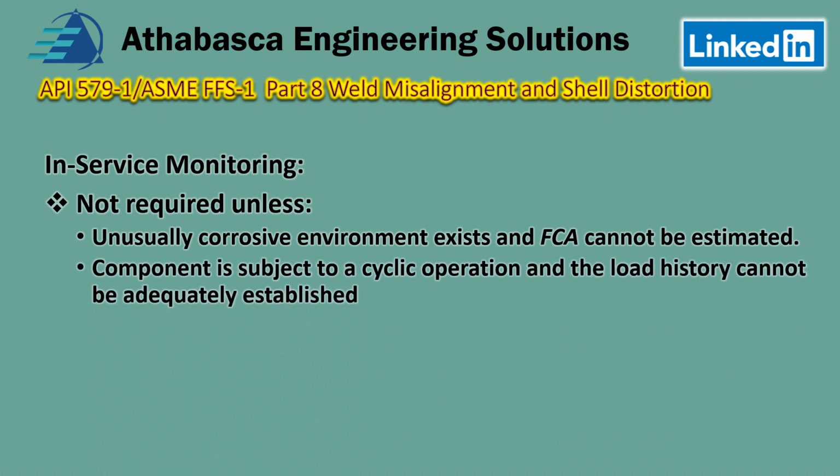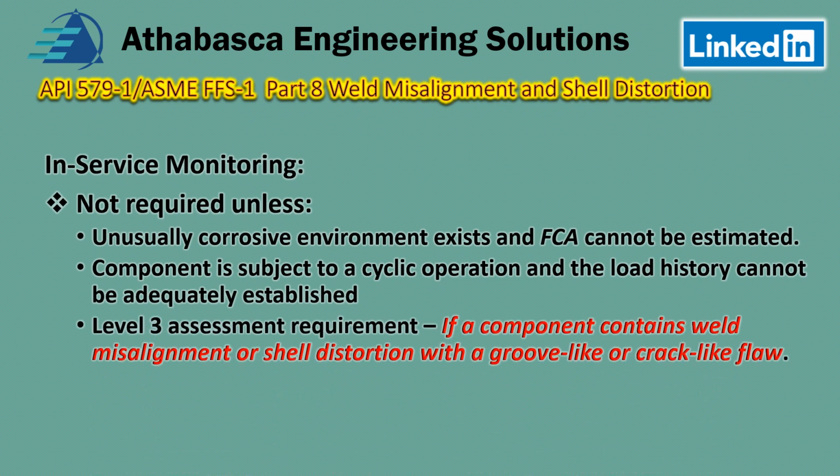Secondly, the component is subject to a cyclic operation and the load history cannot be adequately established. The third one is if there's a level 3 assessment requirement, if a component contains weld misalignment or shell distortion with a groove-like or crack-like flaw.